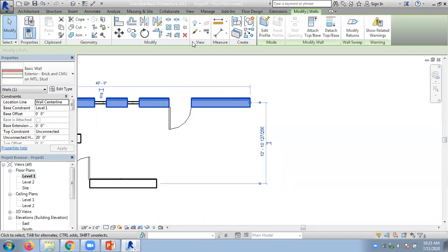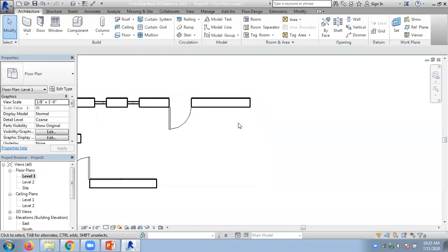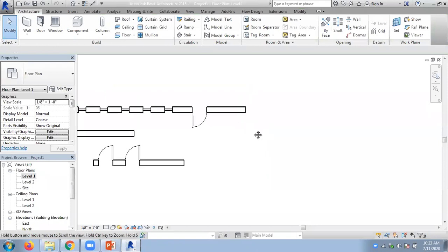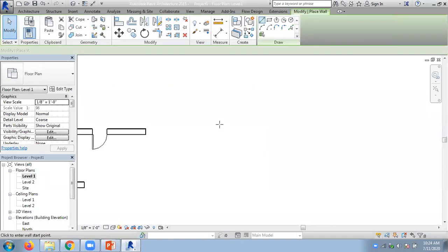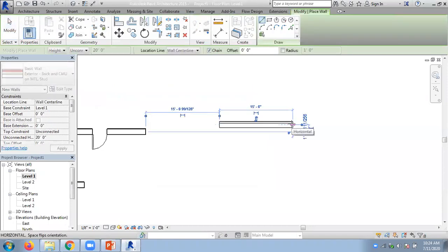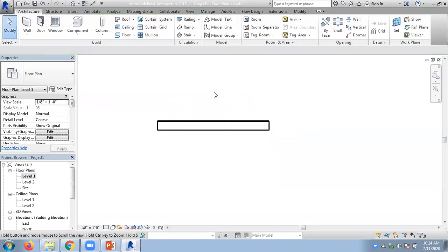We cannot measure the areas, we cannot measure the volumes, and we cannot get a real value of these models. So that's why we don't use the scale tool in Revit heavily like AutoCAD. But we'll see how it works in Revit. I personally recommend not to use the scale tool in Revit.